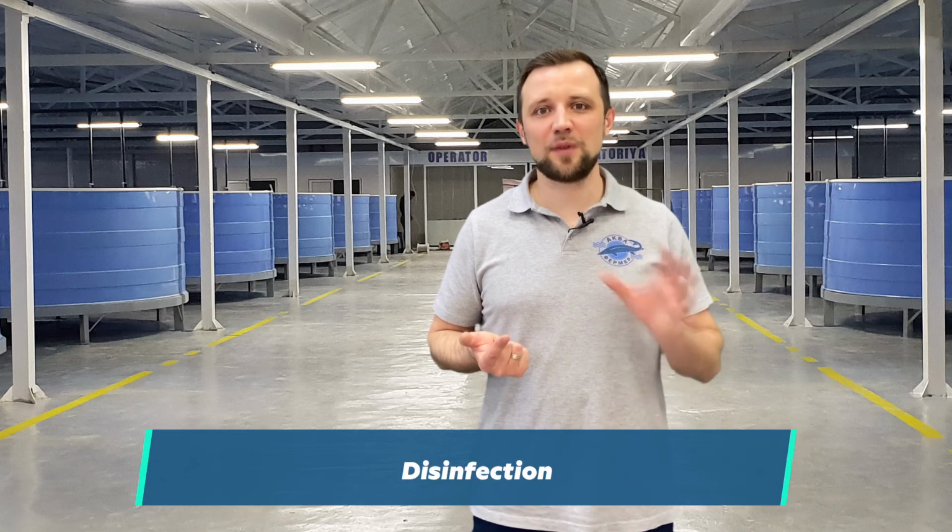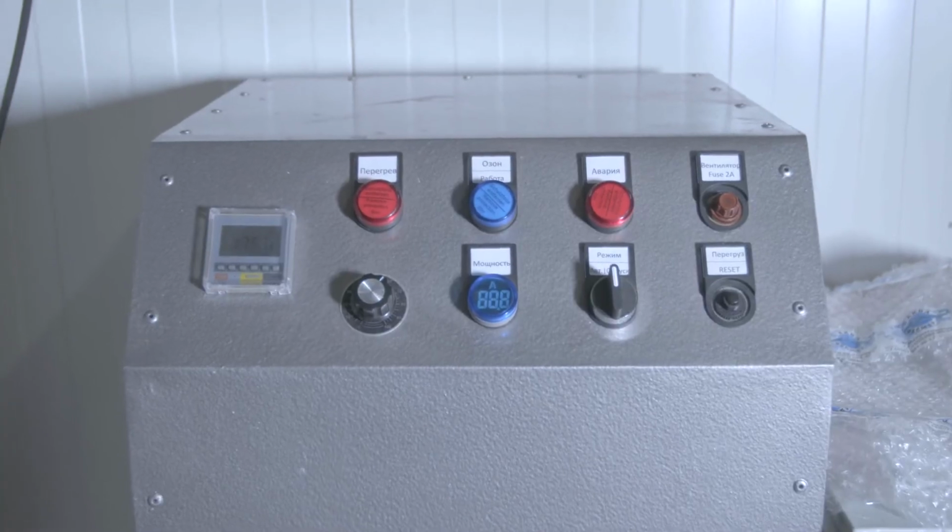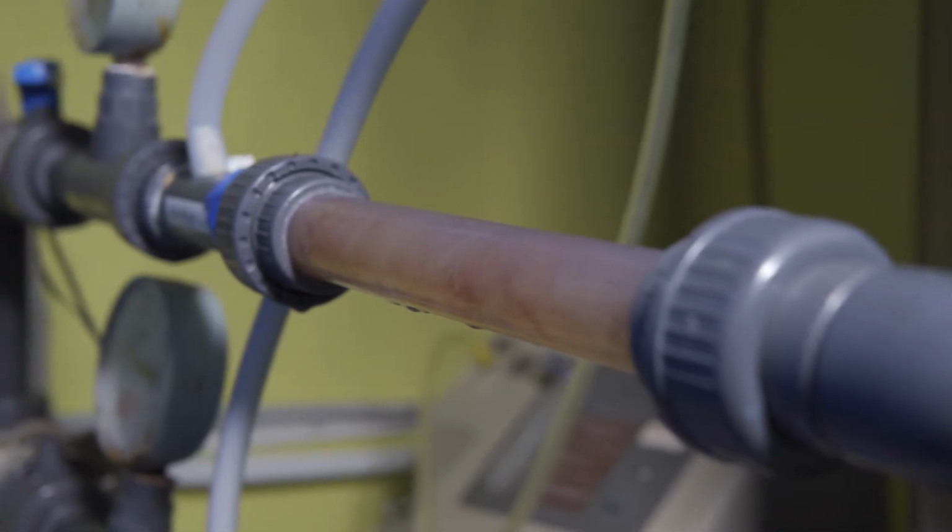Disinfection. Well, as a minimum, this could be an ultraviolet disinfection unit, but I would still recommend to install the ozonation system. Of course, the opponents of ozone will now object and say that it's bad, it's dangerous, expensive, and so on. But firstly, ozone provides more effective disinfection, which is difficult to achieve with ultraviolet separately. Secondly, it clarifies water. That is, it coagulates the fine sediment contained in the water, enlarging it, so that later it can safely be removed from the water by the mechanical filters. It kills geosmins, and generally speaking, it conditions the water.